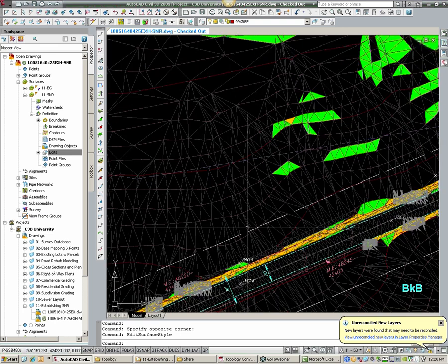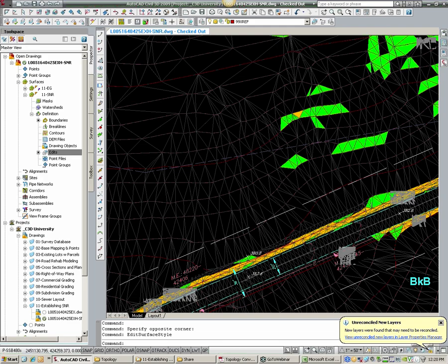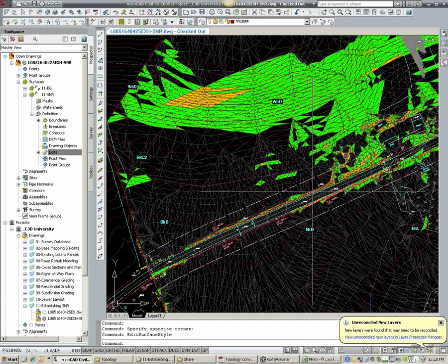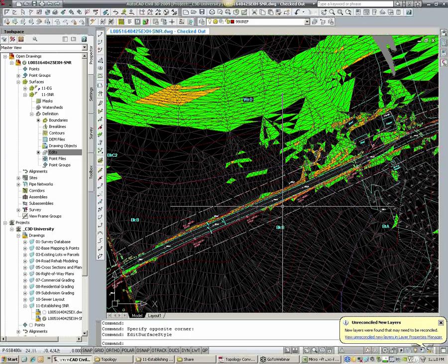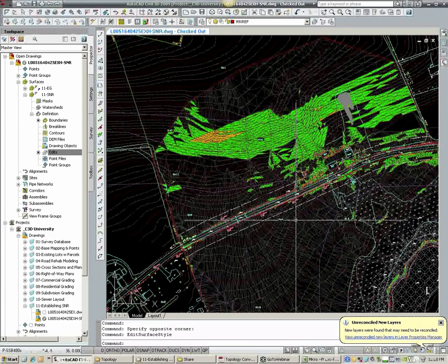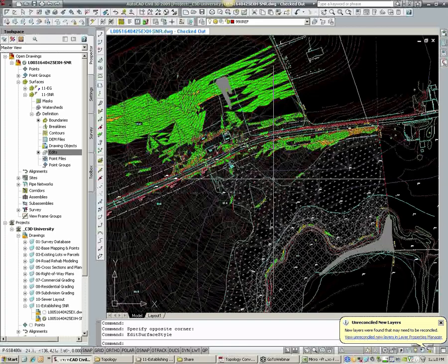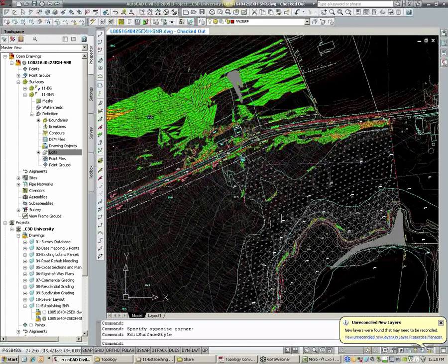And you can see what you get when you create surfaces from contours. It triangulates between each contour because that's all it has to go by. So you do get degradation in your data and in your model. So just try to avoid it. A lot of people say, well, we got it from aerial. It's like, that's not an excuse. You should be getting the information from the aerial. It's like, well, the PM didn't do that. Well, did you ask him to? Those kinds of things. Anyways, not to stick on that too long.